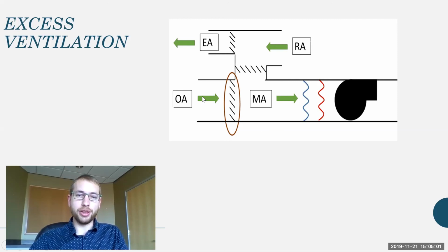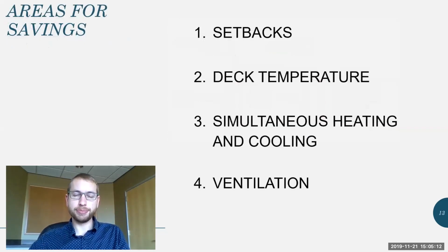So make sure that you have the outdoor air damper closed when unnecessary so that you're not spending extra energy to heat up or cool that down if nobody's going to benefit from it at night or during unoccupied times.